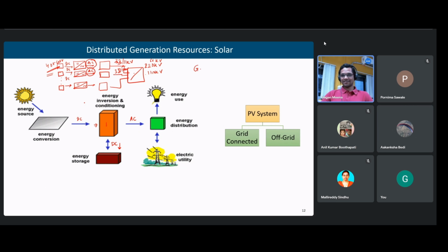See, there are two types of converters: grid forming converters and grid feeding converters. The converters or IBRs that we have right now, as per the standards, are grid feeding converters, and they will feed the required P and Q. Their control system is designed such that their set points are P and Q, the desired active power and reactive power. So they will not care about voltage and frequency. To provide the desired P and Q, they take the V and F reference from the grid.